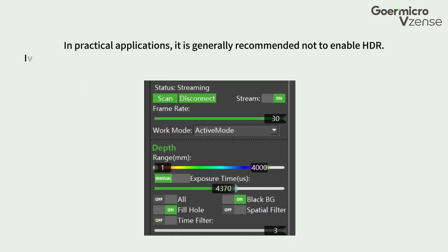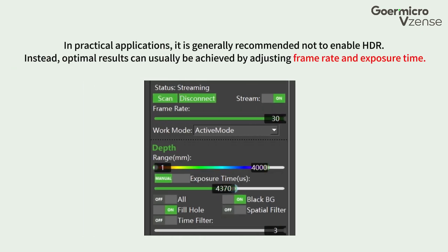Therefore, in practical applications, it is generally recommended not to enable HDR. Instead, optimal results can usually be achieved by adjusting frame rate and exposure time.